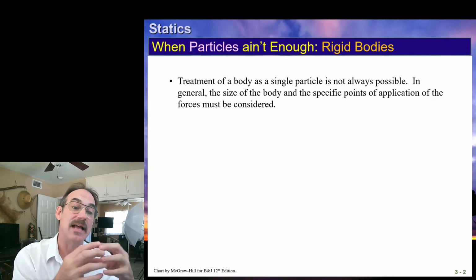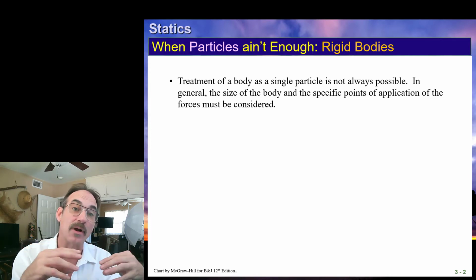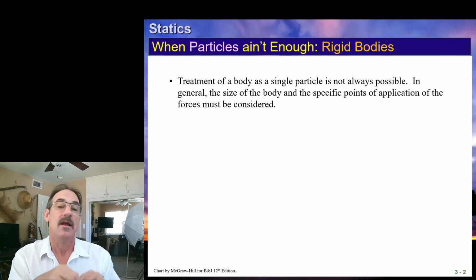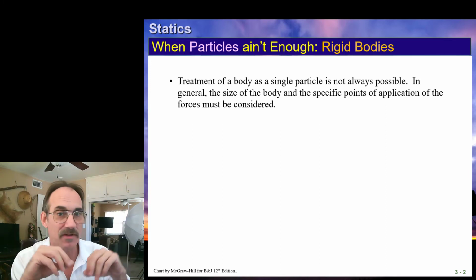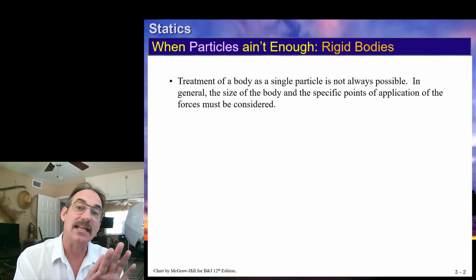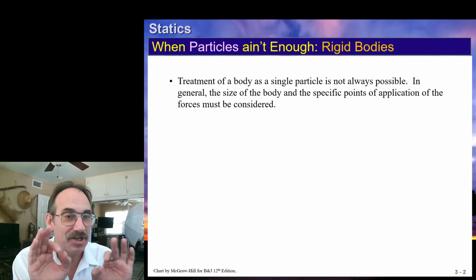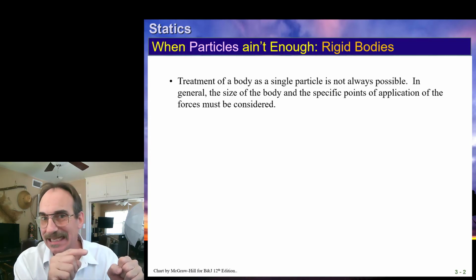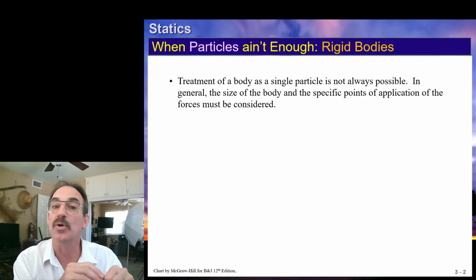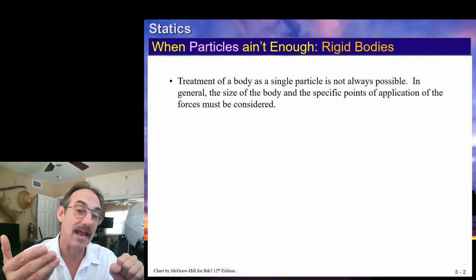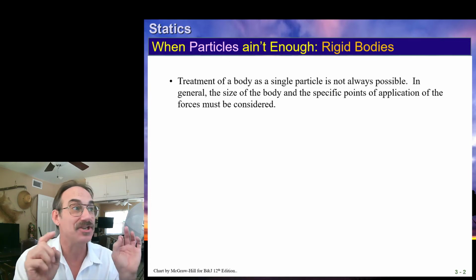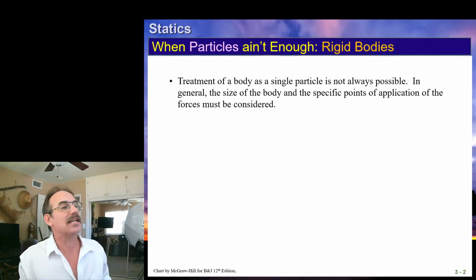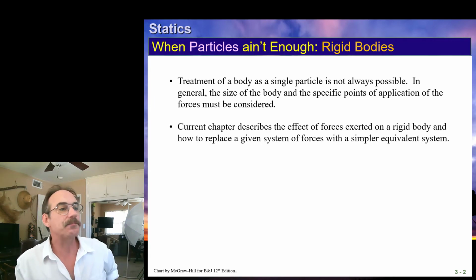Later, we need to drill down when we want to understand what's going on in the aircraft. For example, when we start looking at the detailed forces and moments within an aircraft, we're going to have to analyze it as a rigid body or as a flexible body. So a lot of this has to do with the judgment of the analyst. Can this be idealized? Is treating this like a particle sufficient for the information I'm trying to glean from the problem? Or do I need a higher order idealization like a rigid body? Okay? So that's what this first little bullet is saying.